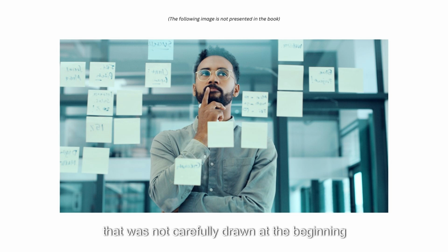A footprint that was not carefully drawn at the beginning of the project could result in the scrapping of fabricated boards weeks later. A bill of materials that was not vetted immediately upon the completion of the schematic design may be harboring components that are obsolete, thus causing the scrapping of fabricated boards, a scramble to find similar components, and a good deal of effort in the libraries, schematics, and layout of the design. In both examples, the failure of earlier processes to consider the process down the road will lead to respins and delays in product releases. There are thousands of decisions, and dozens of subprocesses performed in making a PCB.